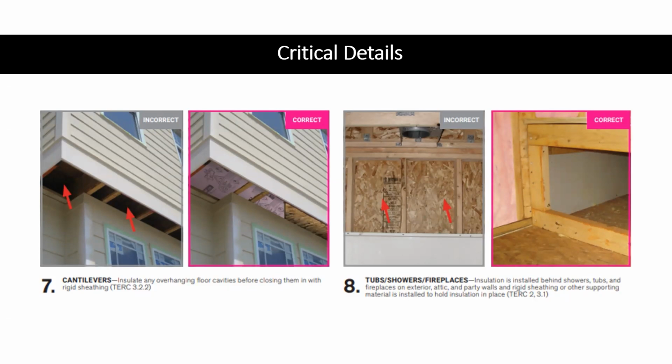And as I told them, that's correct. It can be if they fully fill the cavity with insulation. So if they're using batts and they want to use it as their trash bin, they can just stuff it full of insulation. As long as it's in contact with its all 6-sided air barrier, it is acceptable.